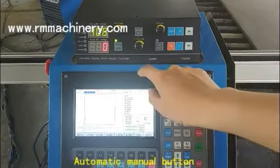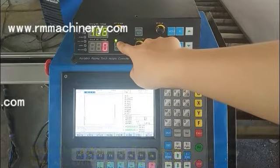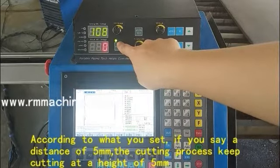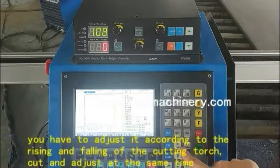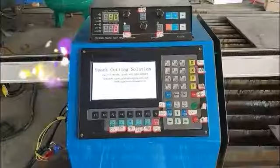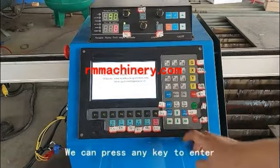Automatic manual button. When the automatic light is on, the arc voltage height controller starts. According to what you set, if you say a distance of 5 mm, the cutting process keeps cutting at a height of 5 mm. When you hit manual, you have to adjust it according to the rising and falling of the cutting torch, cut and adjust at the same time. Entering the boot up state, we can press any key to enter the main interface.